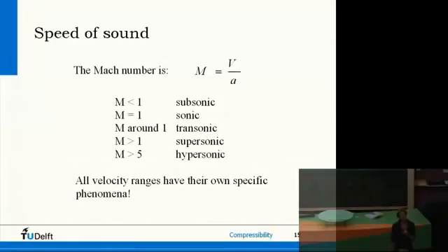And this 100 meters per second is approximately Mach 0.3. So low speed subsonic means the incompressible flow assumption applies when Mach is below 0.3. But when Mach is between 0.3 and 1, you do have relevant density changes already, but the flow speed is, of course, still below the speed of sound, subsonic.